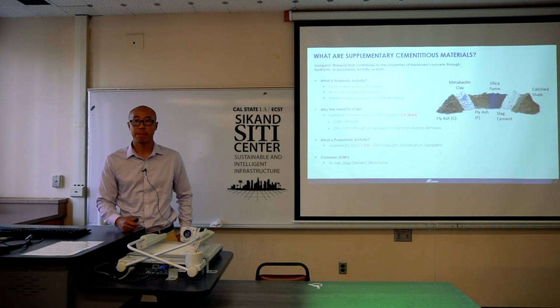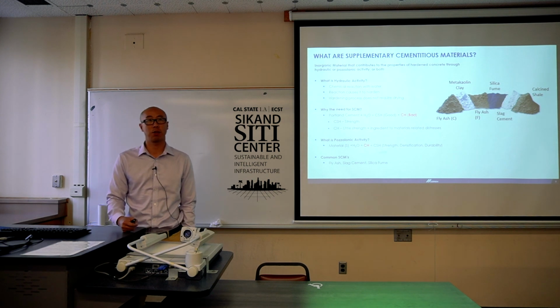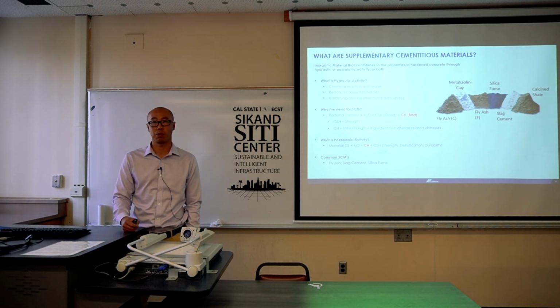Either way, in the industry right now, after you cast the concrete, as long as it has enough strength, you immediately put the curing compound on top of it to prevent losing the moisture. Yeah.